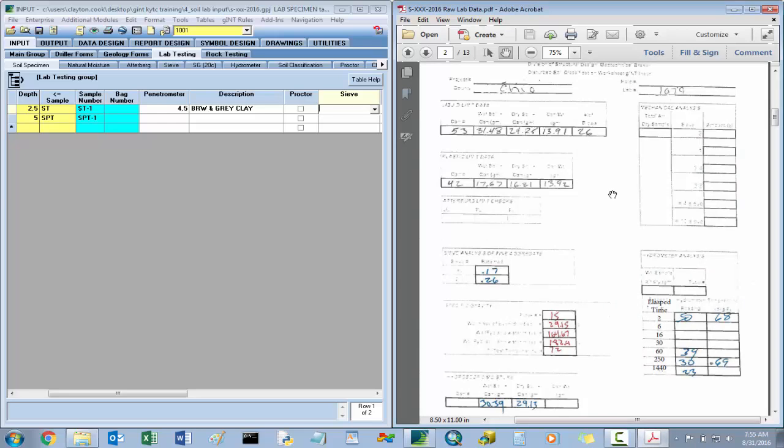If you look on this mechanical sieve here, this is retained number 10, 4, 3/8, 3/4, an inch, 2 inch. For this number 10, there was no material retained, so we know on the sieve drop down that there was no gravel.